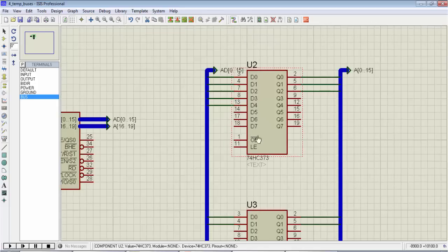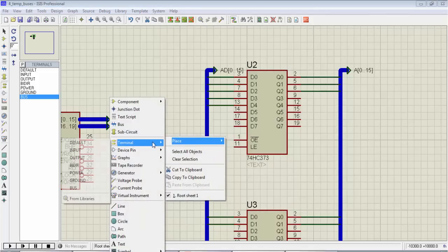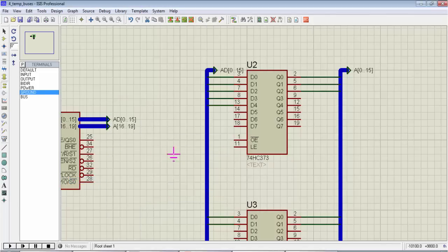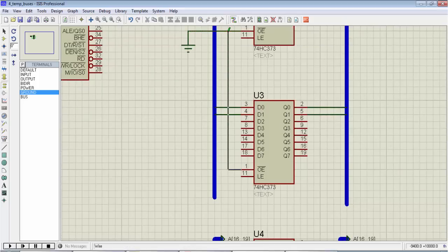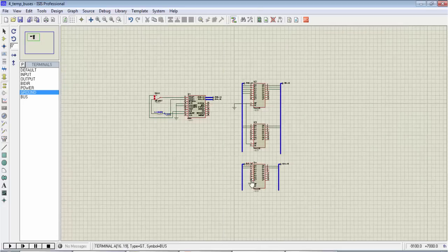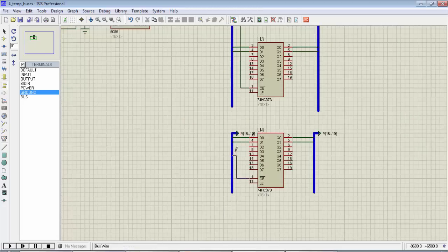As you might notice, we have got 2 control signals, output enable bar and latch enable. So output enable bar acts as chip select signal and we'll be permanently connecting it to ground. So terminal ground, it's an active low signal, so we are keeping it enabled throughout our operation. I've connected it to ground. Same way, the output enable of the second D-latch is going to be connected to ground, and the third latch also we connected to ground.